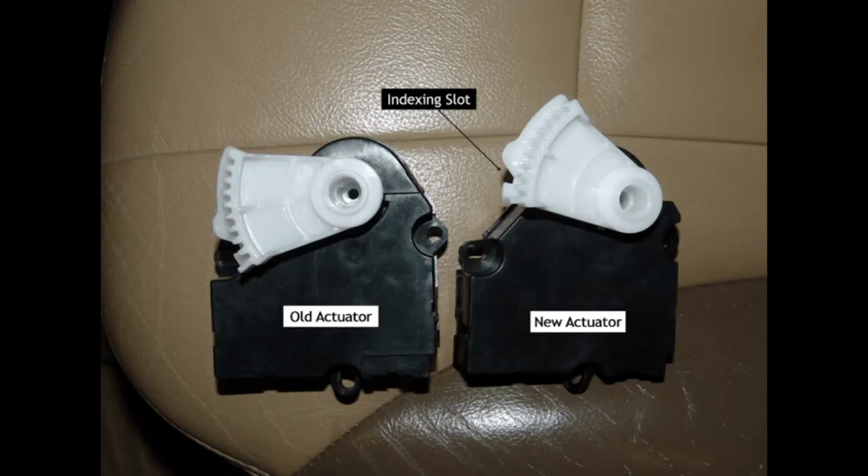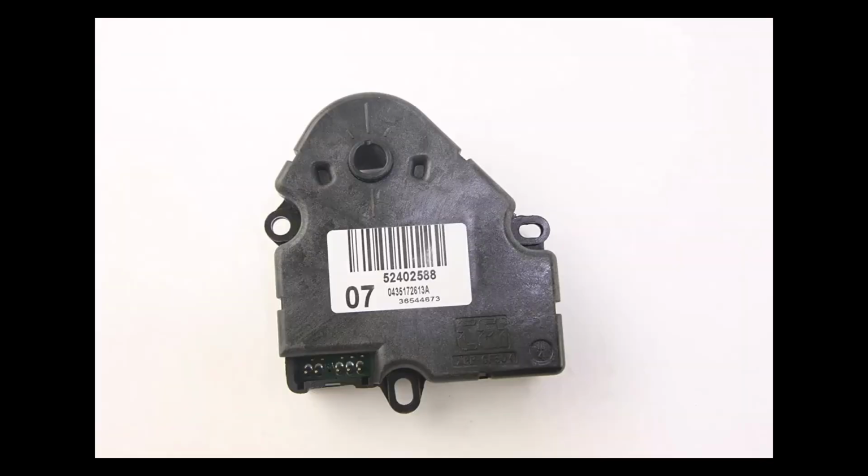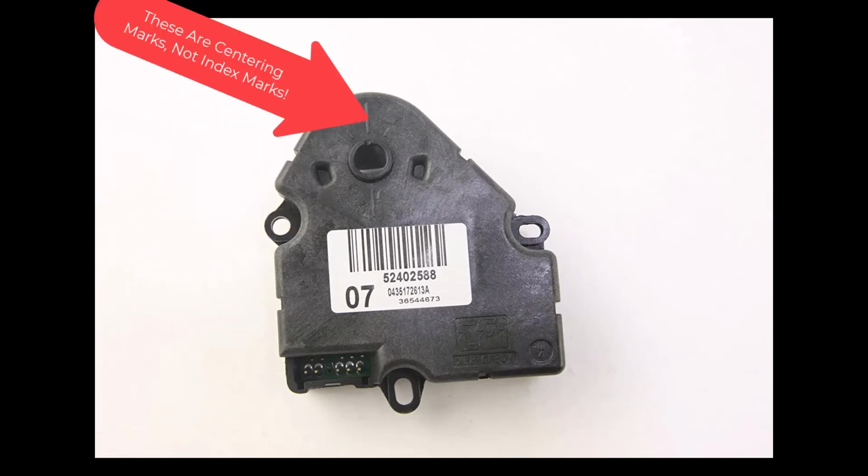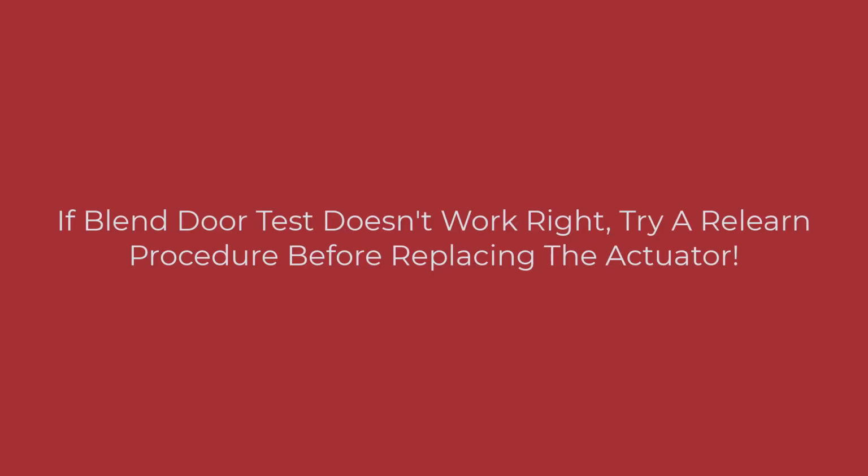Not all actuators need a relearn procedure. The one I'm showing you on screen is from a Ford, and this has index marks on it, so there is no module-based relearn procedure for that particular Ford because it will bump into those marks. But for the GM, again, it rotates 360 degrees. If we don't go through the relearn procedure, we might not get the blend door to open properly. So if we do a blend door test and we're not getting proper heat to come left and right from hot to cold, we may need to do a relearn procedure just to make sure that it indexes properly.